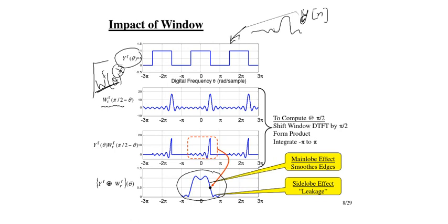We are showing just a single band. You can see that your main lobe has a dip here because the side lobes are also mixing with the main lobe, which brings it down. So instead of this, you are just getting a dip here. This is causing the main lobe smearing, right?